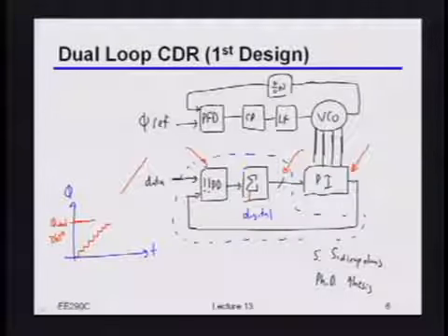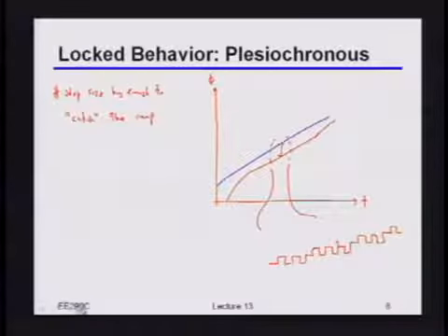So typically you'll not work on this full rate data, but you'll decimate it. You'll send it to some lower rate and then work on things at that lower rate. But again, we'll talk about that in more detail in 1 second. So before we do that, I did want to mention one thing, which is, as I pointed out earlier, there is indeed going to be this static phase error here. And again, the reason for that is fairly simple. So let's just think of this as, again, I know that this is a bang-bang loop with finite resolution and all that.